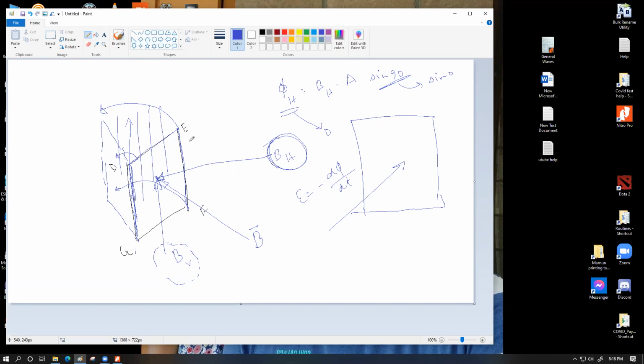Vertical field is cutting, but at any point of time they will produce exactly equal amount of EMF because they will be cutting across the vertical component of the field lines at equal rate, so they'll produce exactly equal amount of EMF. So you will not have a measurable EMF or voltage difference across them because they'll be giving you the same value. So the difference of voltage across these two plates should be zero. They are producing EMF, but they're producing equal EMF at the same time instant.